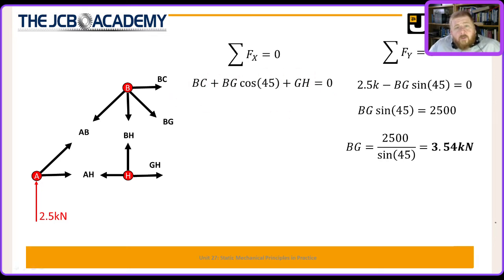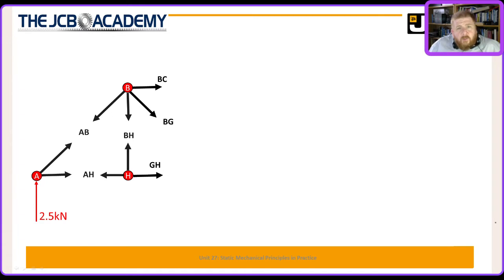So what we're going to do is use the third equation of equilibrium, which we don't use in the method of joints, apart from working out the reaction forces. That is the sum of moments. If we look at the sum of moments, it is the force multiplied by the distance it acts from the pivot. Okay, posh word for pivot, the fulcrum.